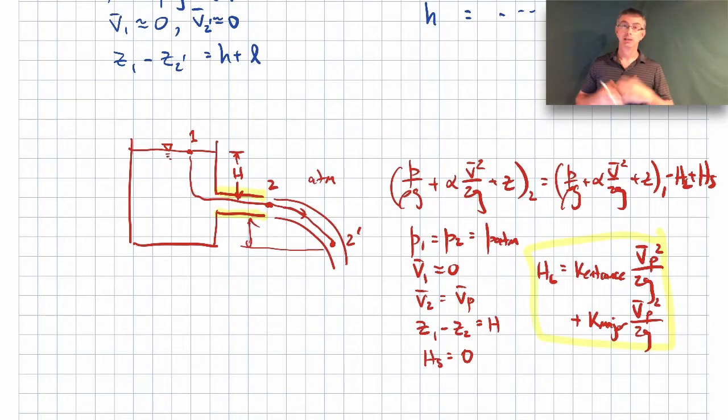So just pay special attention when you are calculating exit losses, just to make sure that, if you're going to put that exit loss coefficient, just pay attention to what's happening to the kinetic energy in the fluid, whether you're dissipating it or not. Okay.